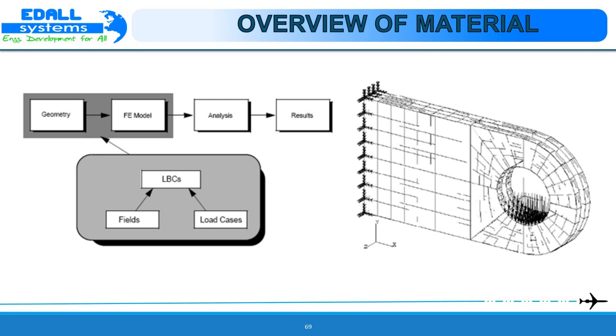The fields and load cases applications. The fields and load cases applications are used together with the loads and boundary conditions application. The figure here shows the relationship between these three applications. In addition to loads and boundary conditions, which remain constant over a period of time and over a particular region of a model to which they are applied, you can also define various loads and boundary conditions, LBCs, that vary temporally or spatially. These are defined using a fields application. This application is described in detail later.